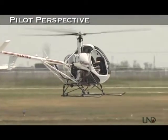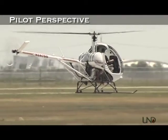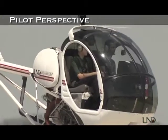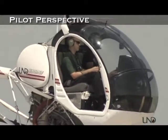The hover taxi is obviously much slower since you're really only moving at a jogging pace, whereas with the air taxi you're anywhere above ETL. It can be anywhere from 20 knots all the way up to 70 knots or faster if you have to cover a lot more ground. Primarily, if you're going to be covering a lot of ground, a pilot will always prefer the air taxi. The only problem is with an air taxi, you need room to decelerate and terminate it back into a hover. With a hover taxi, if you're only going a short distance, it's preferred because there's less setup time and less deceleration time as well.